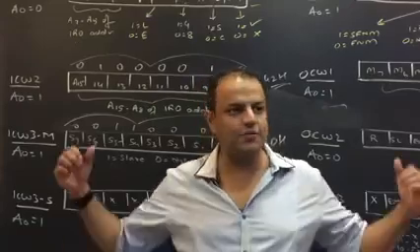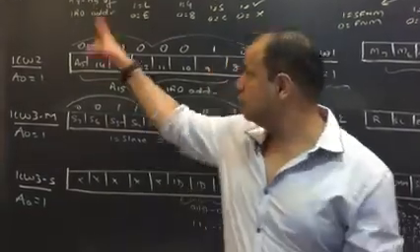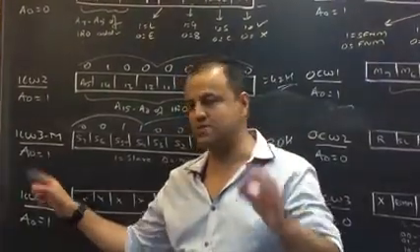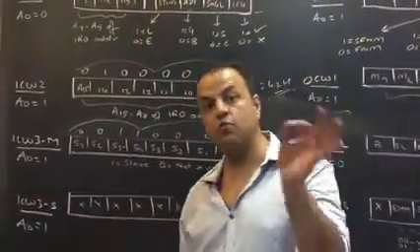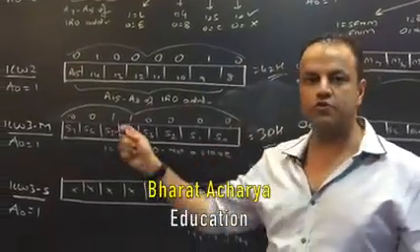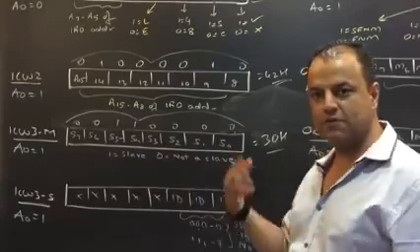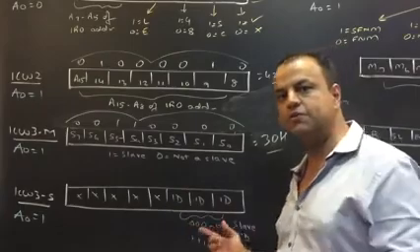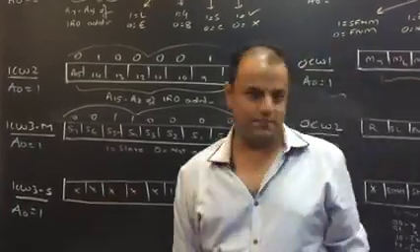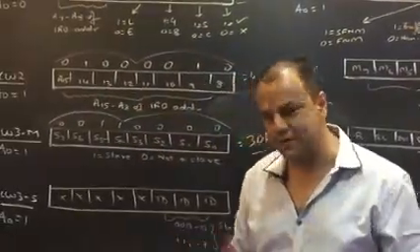Like I said, you have to do this whole initialization for every 8259, for the master also and for the slaves also. So this is common for all. This is the ICW3 given to the master, and this is the ICW3 given to each and every slave. To the master, I will tell you have slaves connected on so and so lines. To the slaves, I will tell what is each slave's identification number. For slave 0, it will be 000, slave 1, it will be 001, last slave 7 will be 111. Are you clear? The remaining bits I don't care about, it doesn't matter. Did you understand why this is only 3 bits? Because the slave ID will be a 3-bit number.